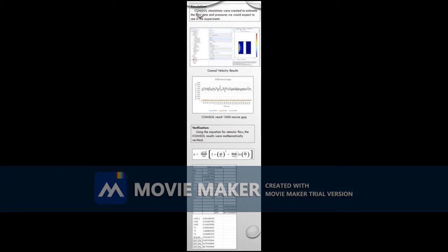Simulation. Nine COMSOL models were made containing 1, 10, and 100 micron gap values with input velocities of 0.1, 1, and 10 meters per second. This is going to tell us the type of flows we will see in the experiment. Below are the COMSOL velocity results and a graph of the COMSOL results for a 1,000 micron gap.